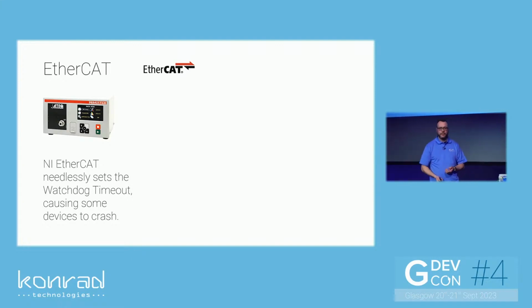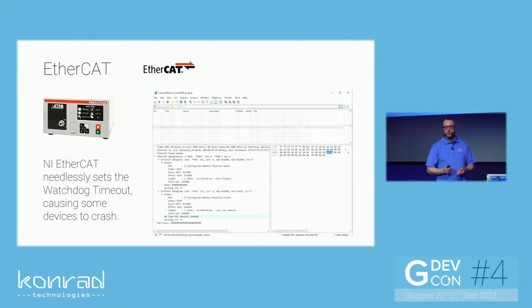We worked with NI, and after lots of Wireshark logging, we found out that, in this particular instance, the NI drivers were setting a variable needlessly on the device, and it was causing it to flake out.